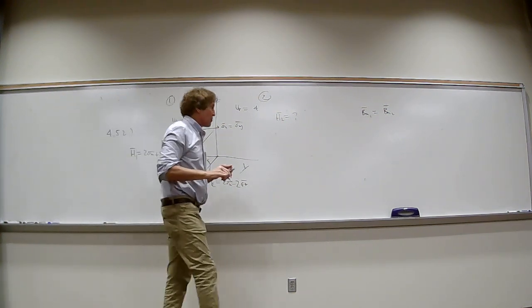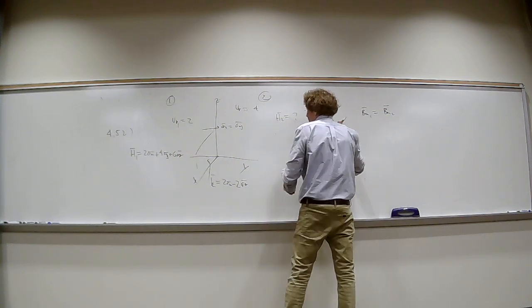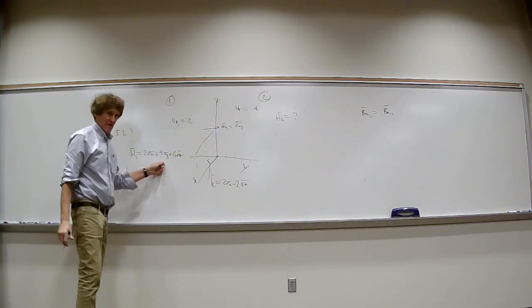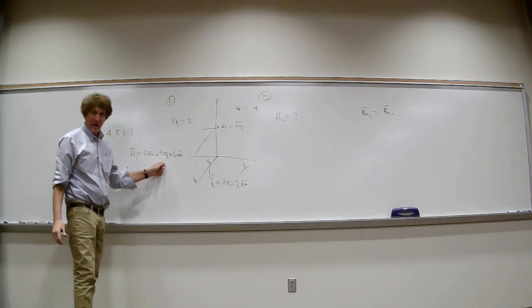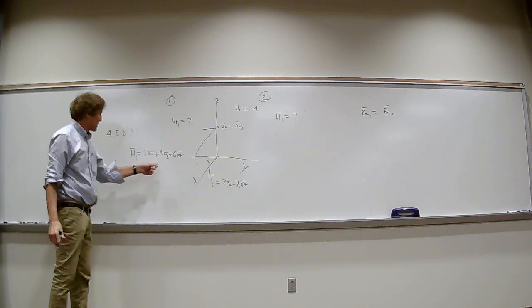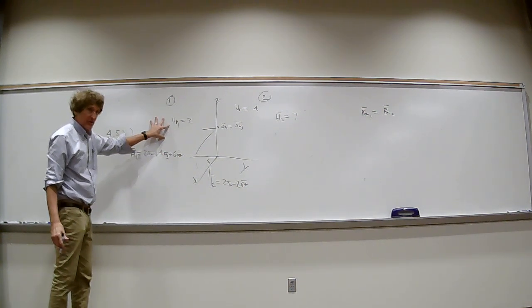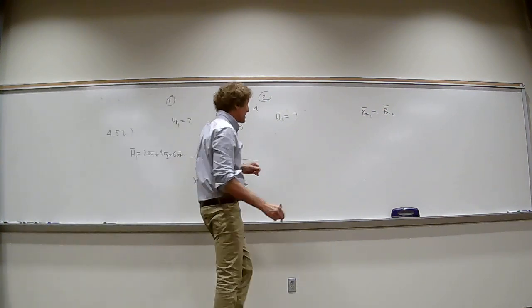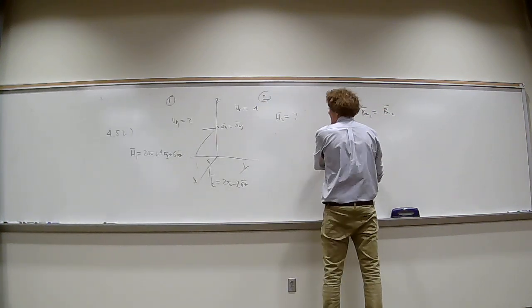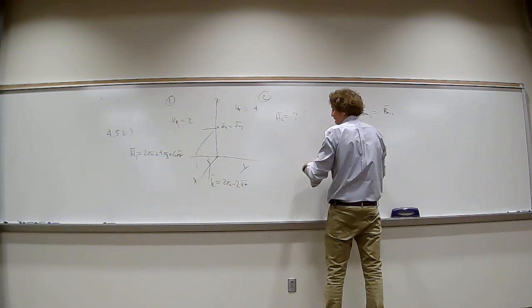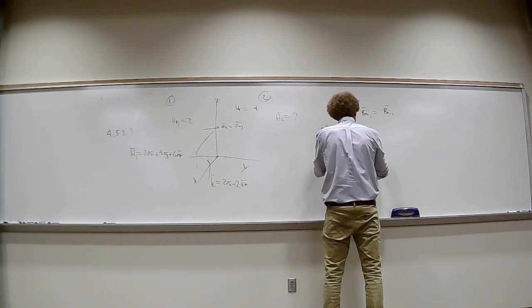All right, so what is B normal 1? The Y component right here is 4 AY. Do you agree? But that's H. For the normal component of the B field, we'd have to multiply that by mu0 times mu relative. So here, we would say 2 mu0 times 4.